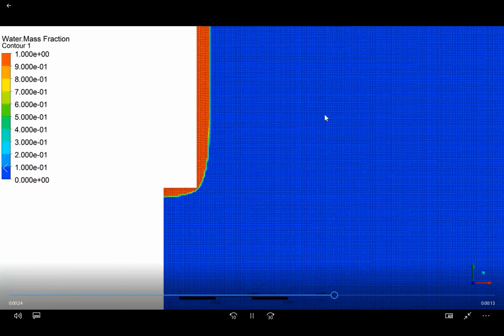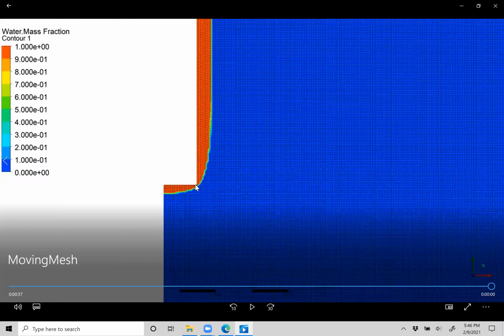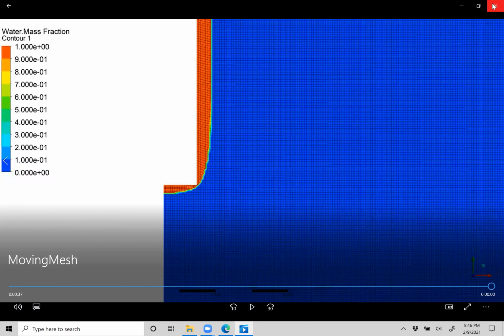And actually what's happening here is you might be able to see it. All these little hash marks are the mesh, and this is an iterative remesh algorithm. So the probe would apply heat until enough of a unit cell layer was able to be melted, take monitor points, remesh the domain, move the probe down, and repeat the process.